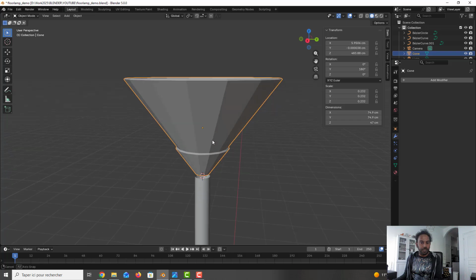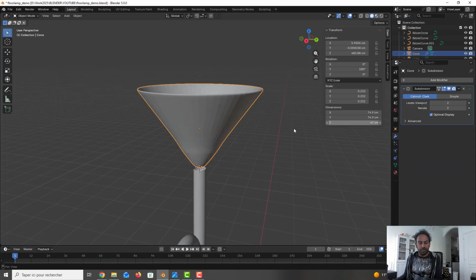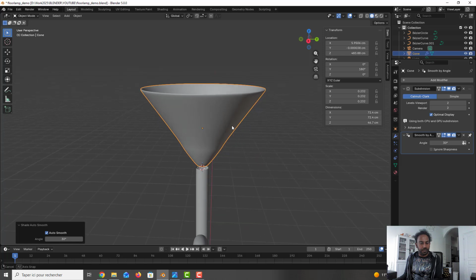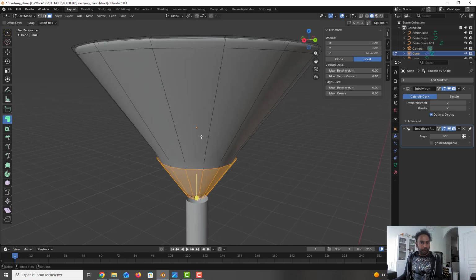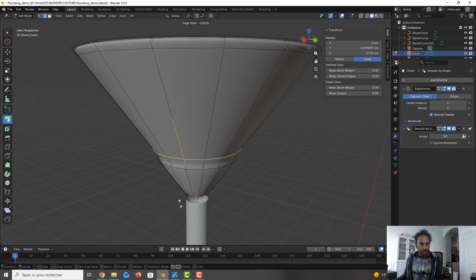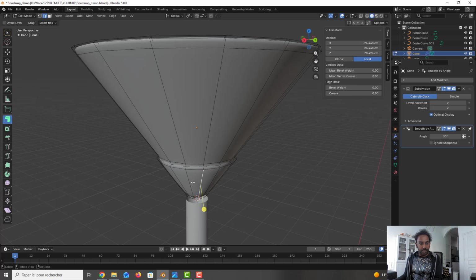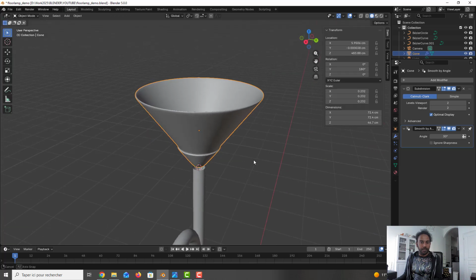After, when it's finished, mesh move, so I will add the subdivision surface on 2. Okay, and we can put shade auto smooth on that. Okay, so if you want more sharpen, we need to add some cut loops. So Ctrl R, I will add one maybe on below like this, and I will add one on the top like this. Okay, it's exactly what we want.